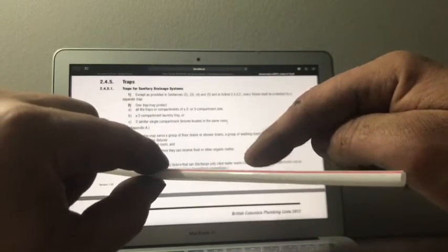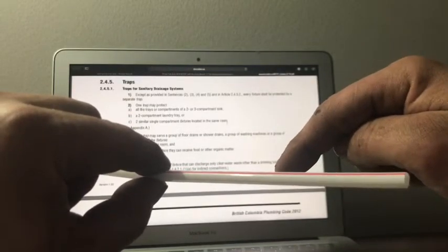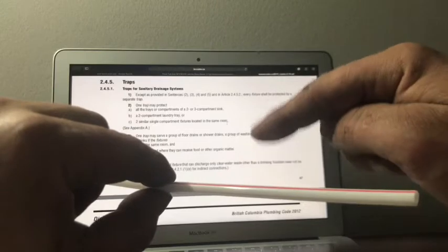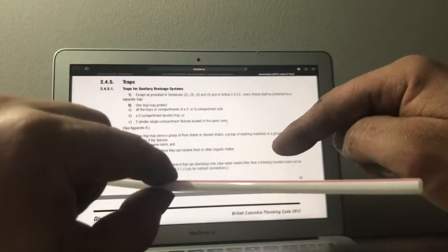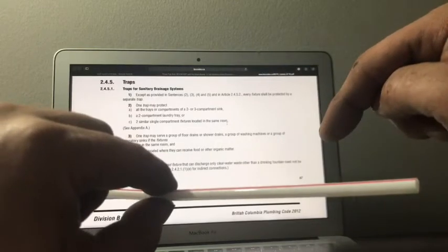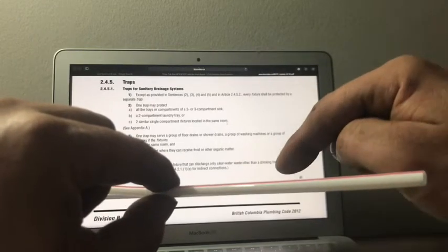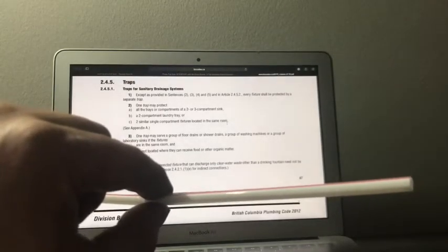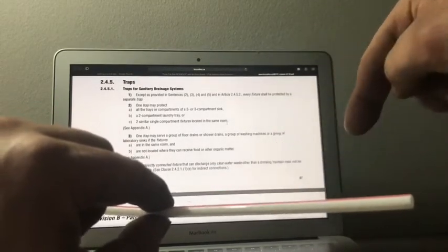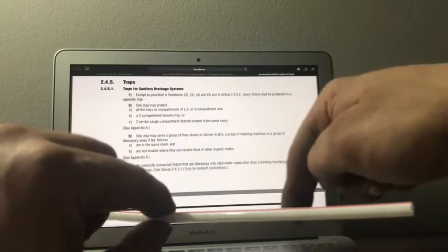Okay, so you go P trap, sanitary T, jump over what you're trying to get over, straight up for a clean out, off that branch of the sanitary T, 90, another sanitary T, 90, pick up your second fixture, and right off the top of the first fixture, obviously we would be picking up 2 fixtures off of this one trap.